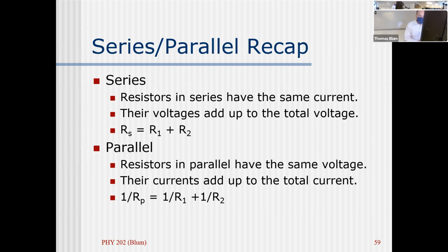Series is the same current. The voltages add up, and the equivalent resistance is R1 plus R2. Parallel, the resistances see the same voltage, it's the currents that add up, and the equivalent resistance uses this reciprocal formula.